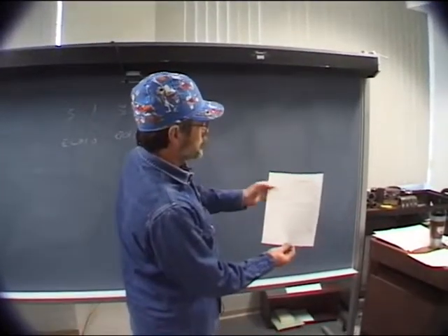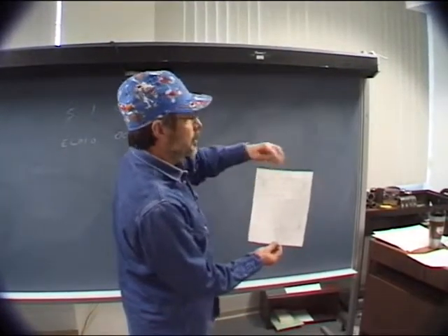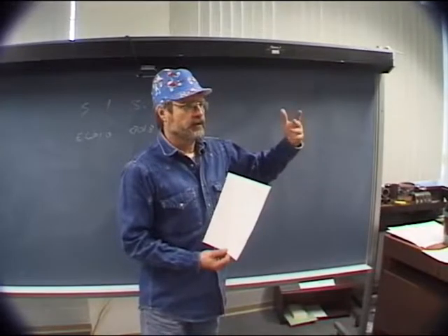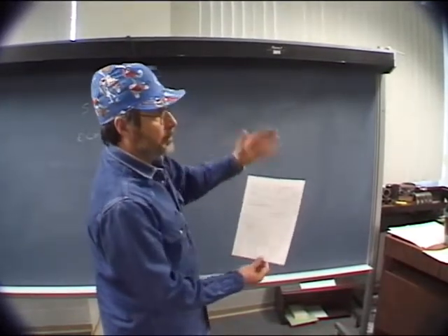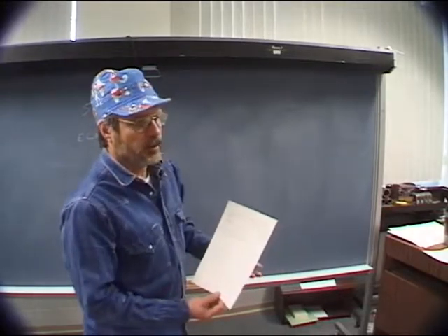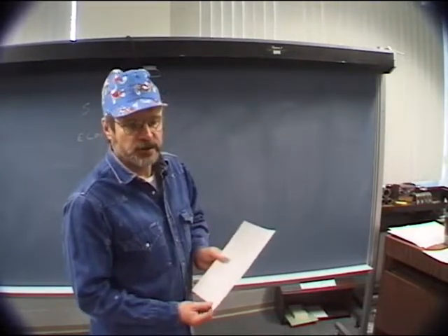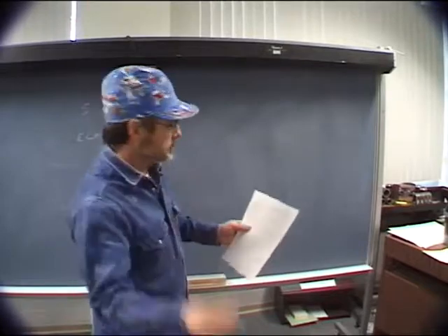We have position of welding. Well, we qualified it in the vertical up position, but we know that we've matched the mechanical properties, and so it can be used in any position: flat, horizontal, vertical, overhead, doesn't matter.